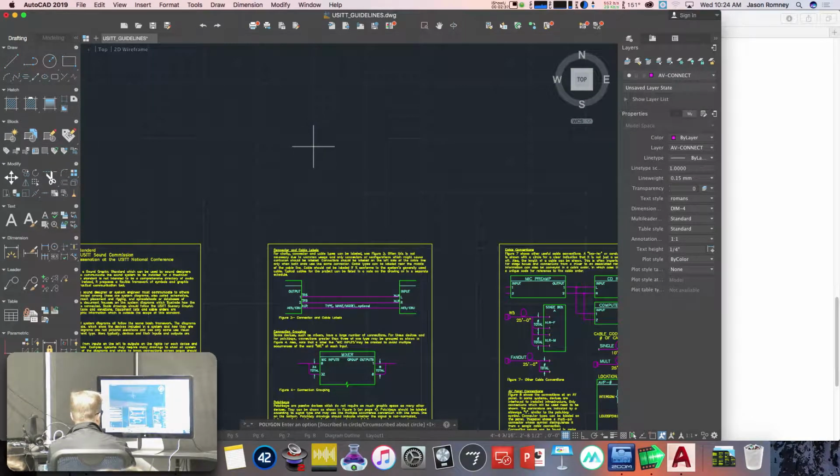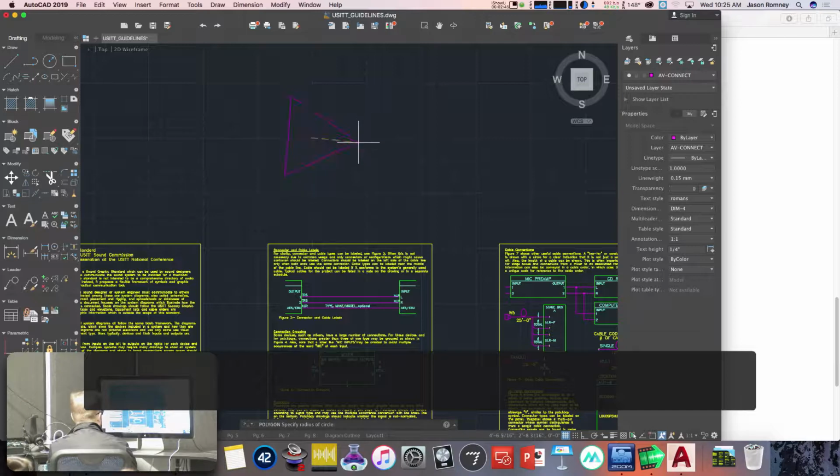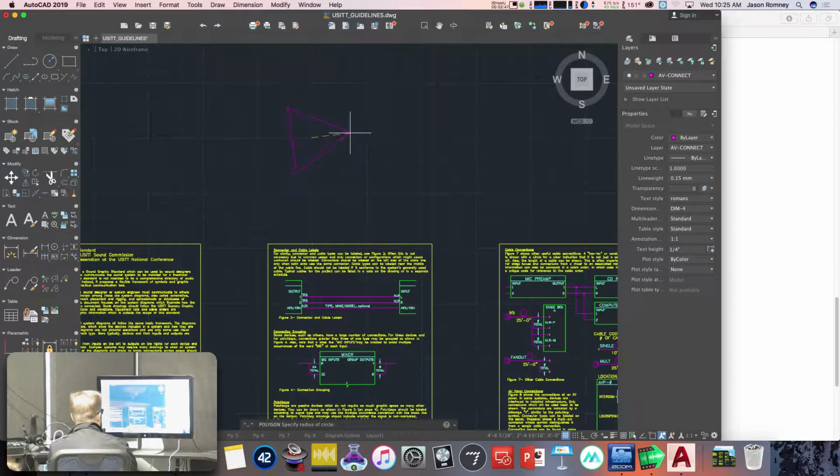So you click, and then you want it inscribed or circumscribed about a circle. Just inscribed is fine. And then you can drag and move around and get your triangle whatever size you want and whatever direction you want it to point. And it automatically is equilateral no matter how big you make it. Cool, right? Wow. That would have been handy, wouldn't it?